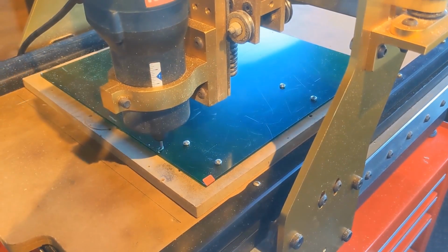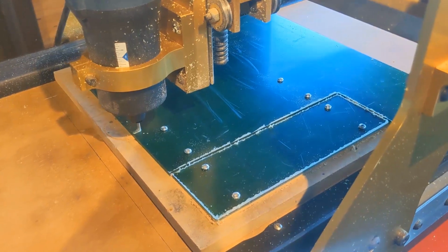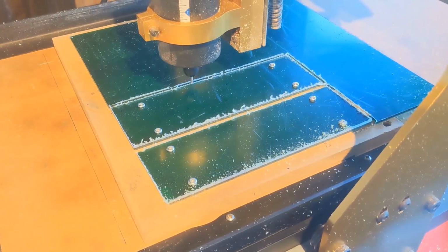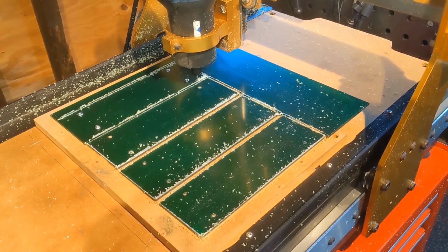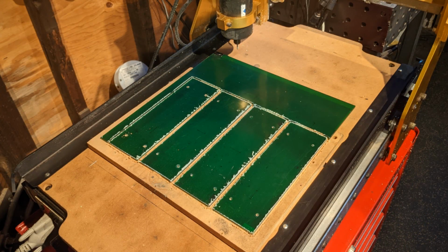I'm also using the CNC to cut out transparent green plexiglass covers for the 4 displays, and cutting the 4 holes that match the enclosure and the OLED mounts. It's hard to cut plexiglass by hand, so the CNC is a great solution, and it allows me to give the covers a very smooth, rounded corner. Okay, 4 identical covers ready to go.